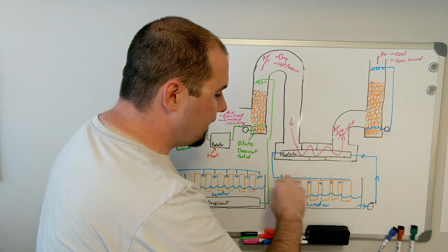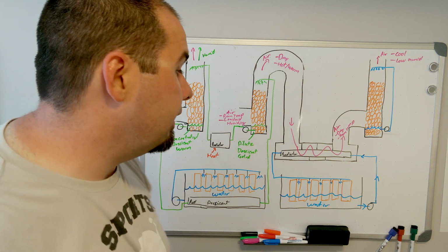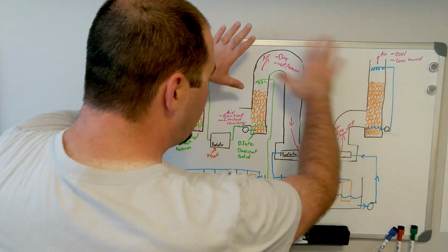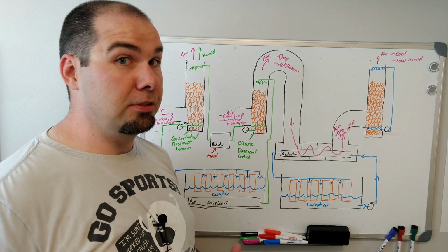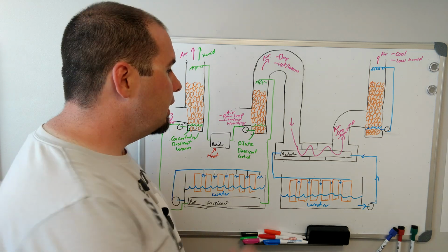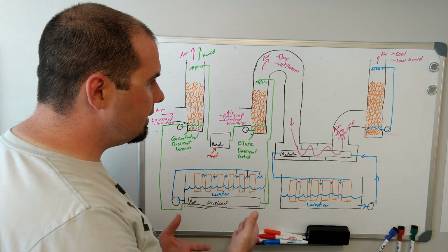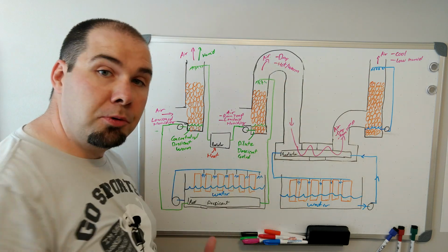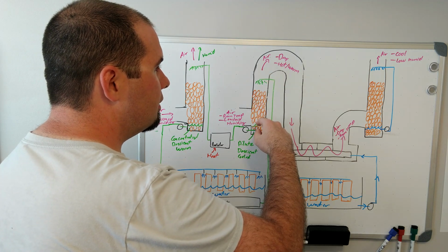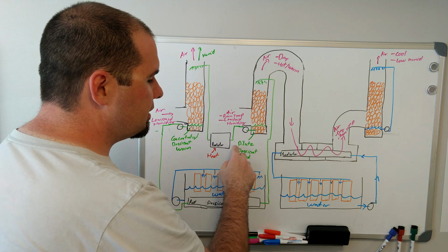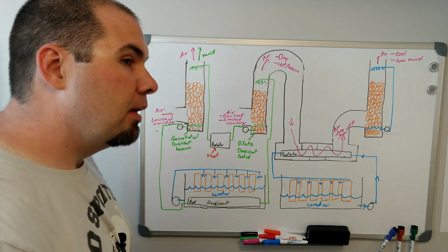And then the radiator comes back and goes into swamp cooling mode. So it's spraying, evaporating, and cooling that water that just received all that heat. So we now have this loop taken care of. For this desiccant loop, we're going to actually need the desiccant in two states to do what we want. In this first state we already mentioned, and what we need is cooled desiccant so that as it runs through this swamp cooler effectively, that it can pull in that water, and then that results in its dilution. It's still cooled, but it's dilute.